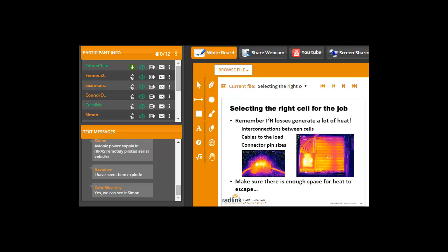Now, I was at the Chinese battery factory only a few weeks ago because we were manufacturing some battery packs, and I use a FLIR camera for all of my diagnostic stuff. What we have here on the right-hand side is you can see the cells underneath the plastic case. They're glowing because they're warmer. So the black areas are cool. The yellow areas, the brightest yellow areas, are the hottest part.